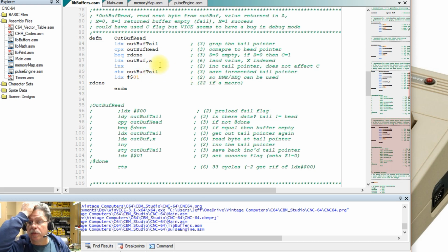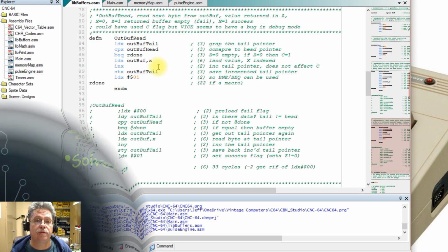Luckily this works, because we saved about 11 cycles there, so that's 11,000 clock cycles a second. Let's say average instruction length is 4, so we've bought ourselves maybe 2,000, 2,500 more instructions that we can execute every second. So this was a significant change.